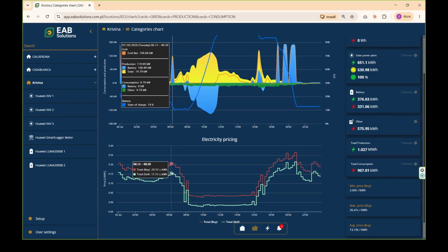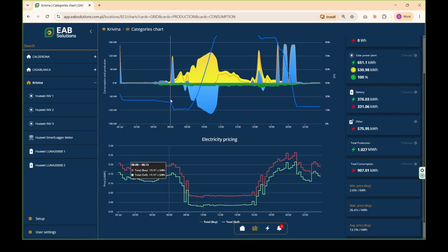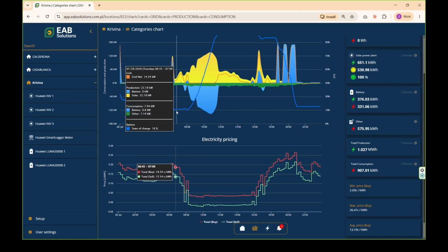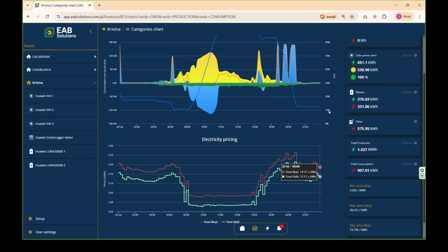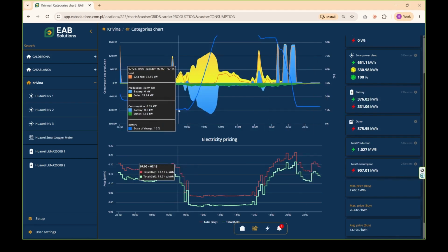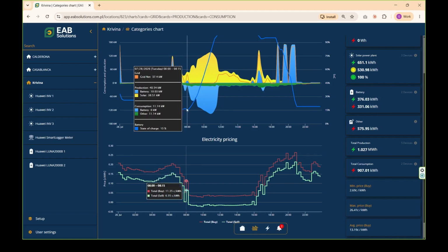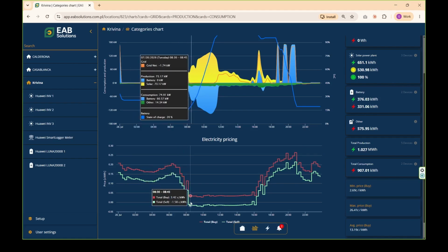We have 15 cents. They're paying us 15 cents for electricity, so we empty the battery. Here you see the blue line go down. It has emptied part of its energy. Now the battery is almost empty, at 15%. You can see the battery state of charge on this axis here. 15, 30, 45, 60%. So, with the battery as low as possible, we wait for prices to fall.